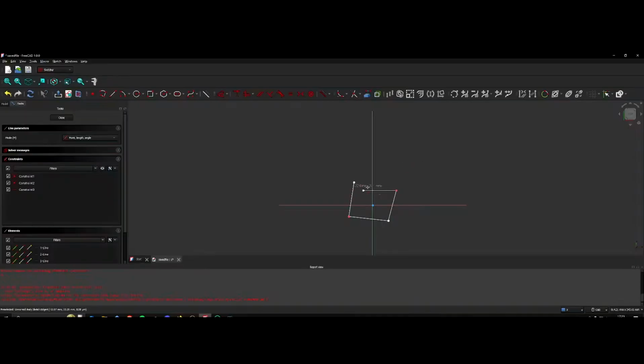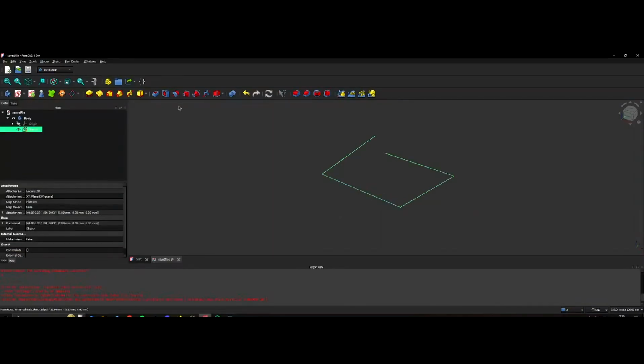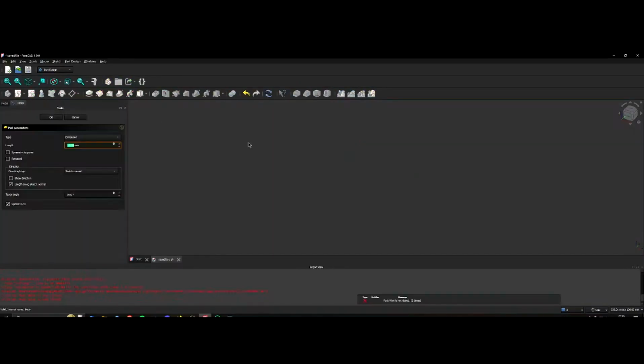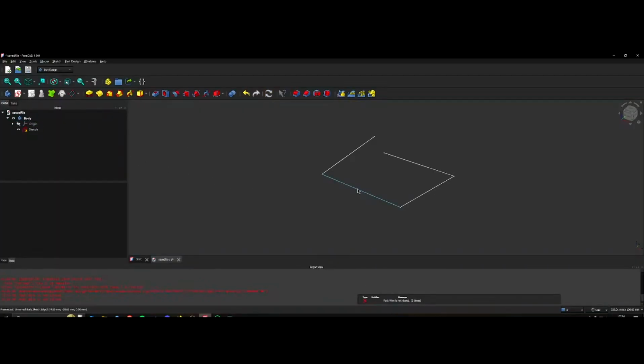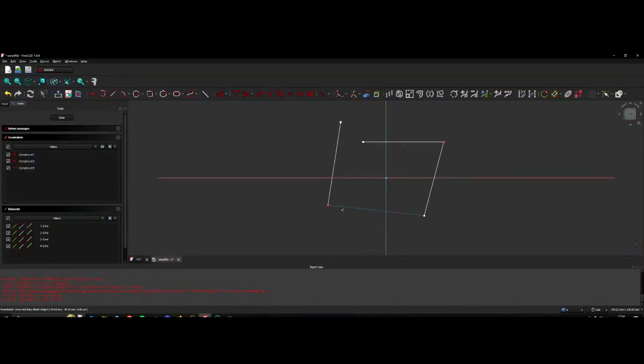For example, if you try to draw a shape with lines, but one end of a line doesn't connect with another, what we call coincidence, then the shape you have created will be impossible to extrude, or in FreeCAD, pad, because the shape is incomplete. All points must connect. They must be coincident in order to be used. Constraints are also used for precise measurement and to clearly define tolerances. With that out of the way, let's create a sketch.